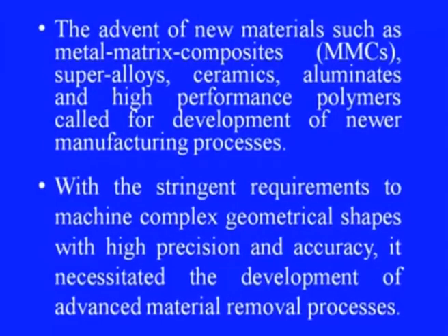The advent of new materials such as metal matrix composites, popularly known as MMCs, superalloys, ceramics, aluminates and high performance polymers called for the development of newer manufacturing processes. Some of these materials, these MMCs and superalloys, are mostly nickel based alloys. These are very difficult to machine in the conventional ways.